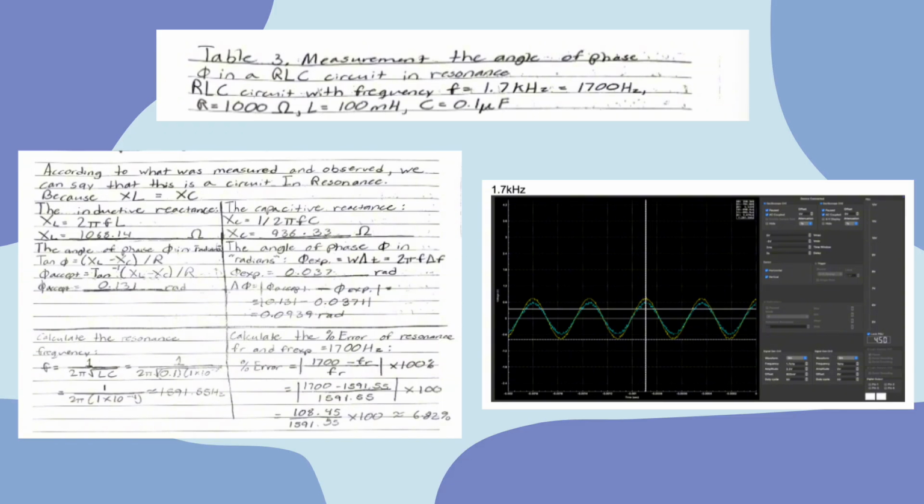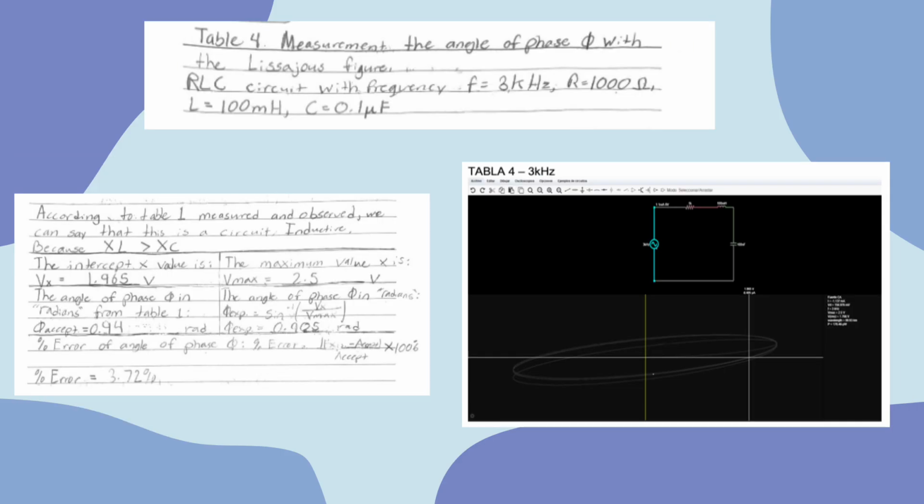In this experiment, the main instruments were the oscilloscope and signal generator. The oscilloscope introduced uncertainty related to time resolution, voltage sensitivity, and interpretation of waveforms, which affects phase measurement precision. I calculated reactance, phase angle, resonant frequency, and percent error. Both systematic and random errors were present. Systematic errors include calibration and component tolerance, while random errors come from reading uncertainty and signal noise.